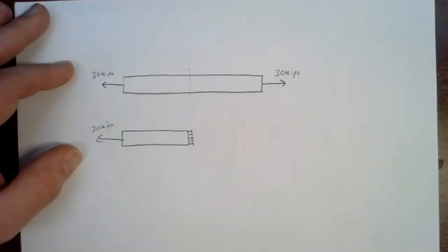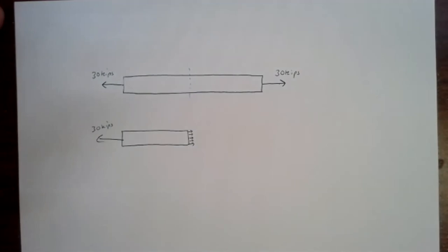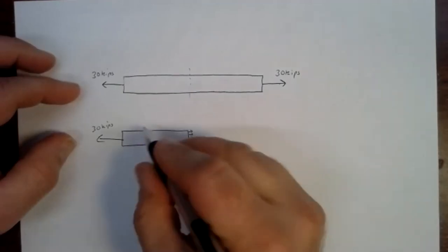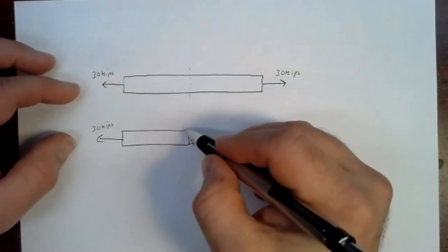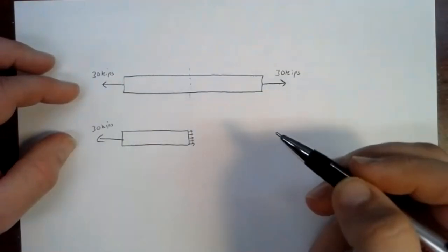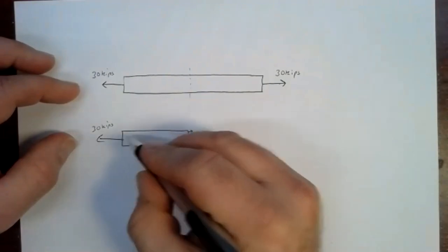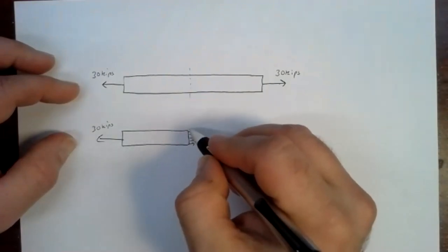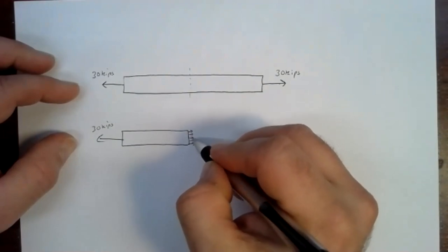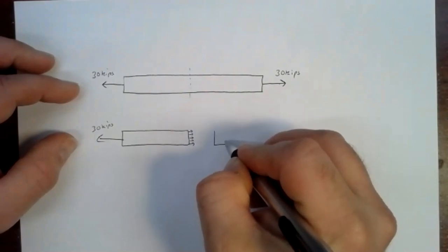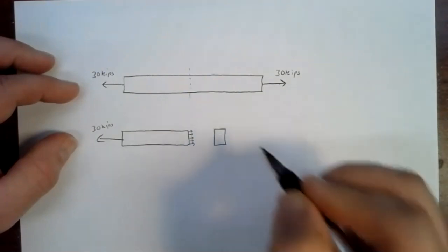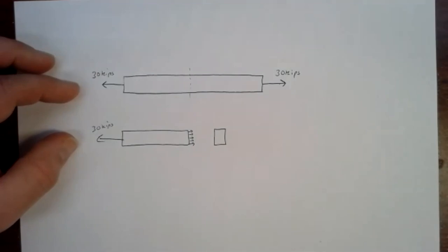If this piece of the beam is in equilibrium, and that's a fundamental idea that we've had since the beginning, that if a structure is in equilibrium, every piece of it must be in equilibrium. If this part to the left of my cut line is in equilibrium, then whatever this adds up to must be 30 kips. What it ends up being, as long as we're far away from the ends, is that force of 30 kips is spread uniformly across the area. So if we have, for example, some shape, it really doesn't matter the detail of the shape as long as we can figure out what the area is.